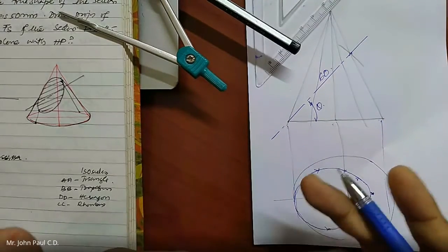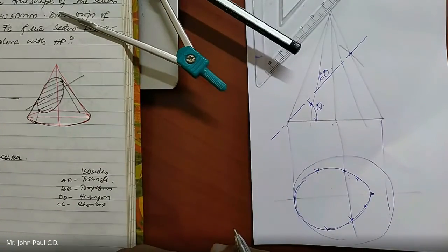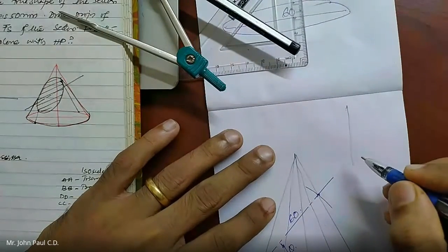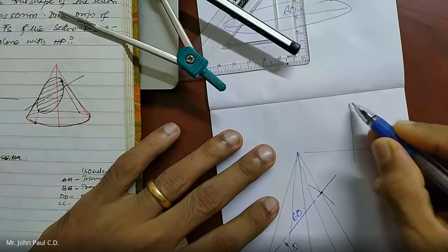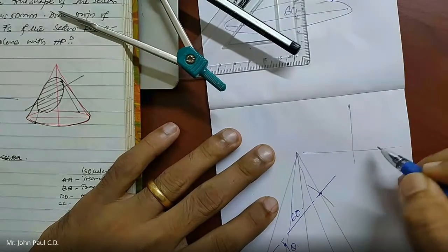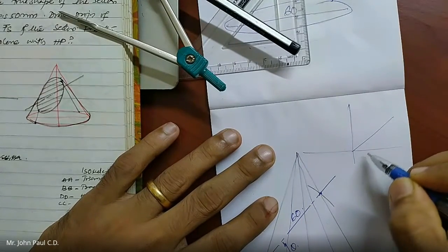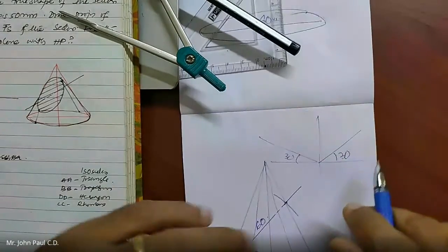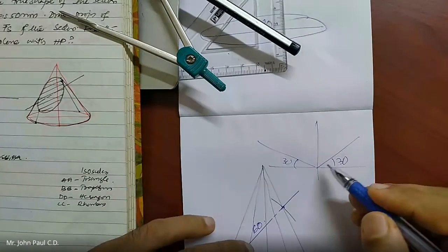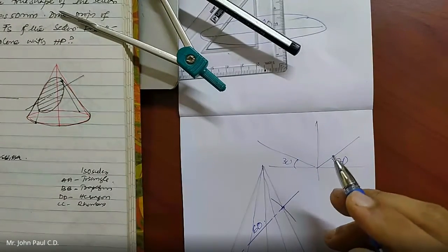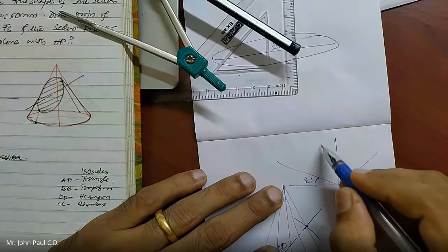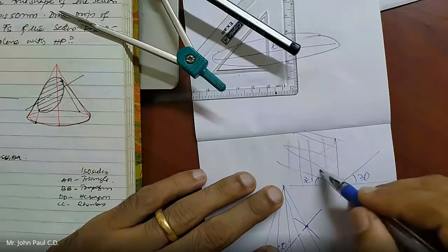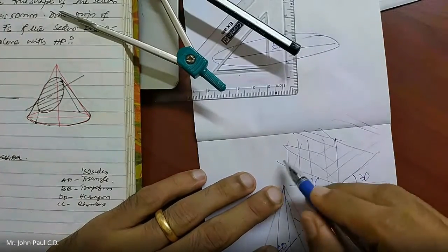Now, if you say you cannot draw without it, you can draw, but it will take more time because you need 3 axes in order to draw isometric projection. One will be perpendicular to the baseline, one will be at an inclination of 30 degrees, and another one at 30 degrees. For all the dimensions you have to draw these. So in isograph you have a number of vertical lines, a number of 30 degree lines, a number of 30 degree lines like this. So anywhere you can draw.